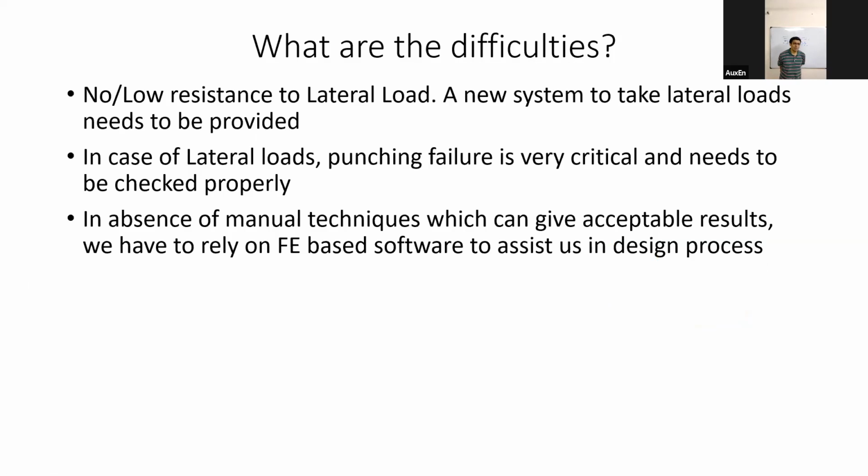Of course, when there are good things, there will also be bad things. And what are the bad things or the difficulties of providing a flat slab system? The biggest disadvantage of a flat slab system is a very low resistance to lateral loads or earthquake loads.